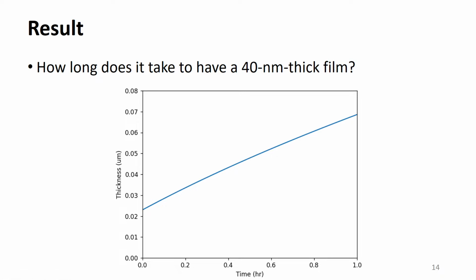Of course, it is well known that the Deal-Grove model fails near 0 hour because in reality, in experiments, a very rapid increase of oxide thickness is observed. However, our Deal-Grove model cannot describe this superlinear oxide growth quite well, so we must modify it a little bit, but we will not consider it because it seems to be a little bit beyond the topic of our lecture.